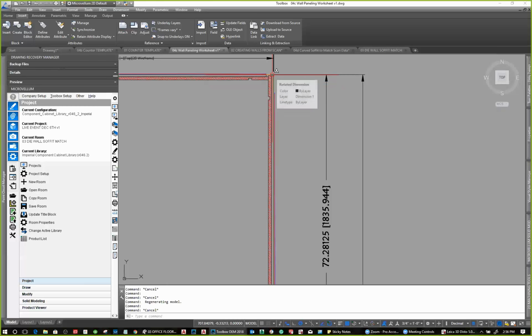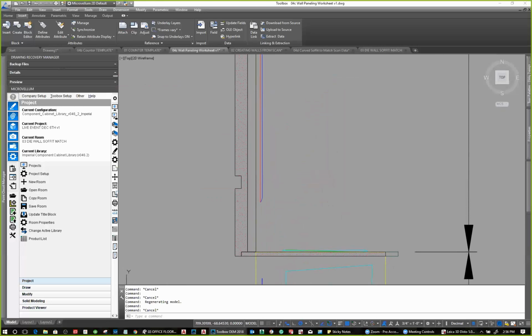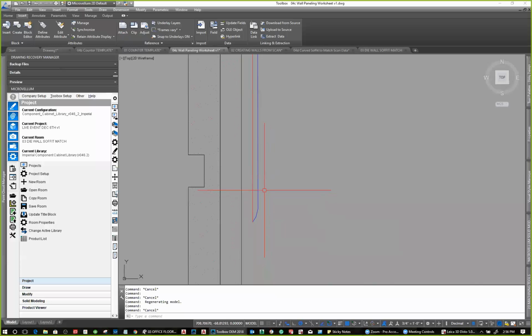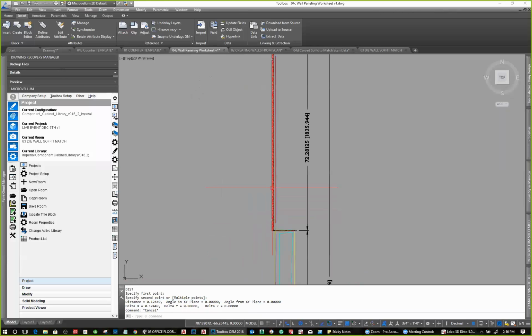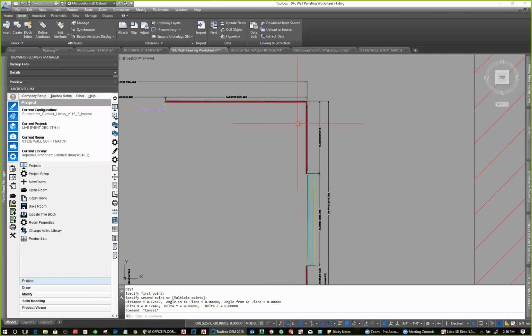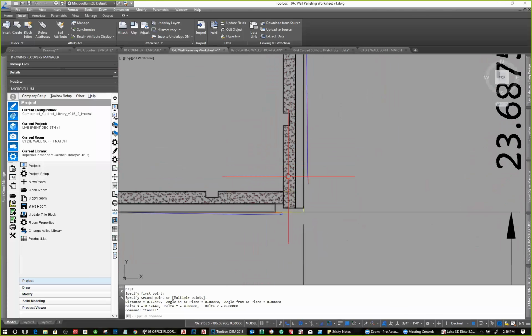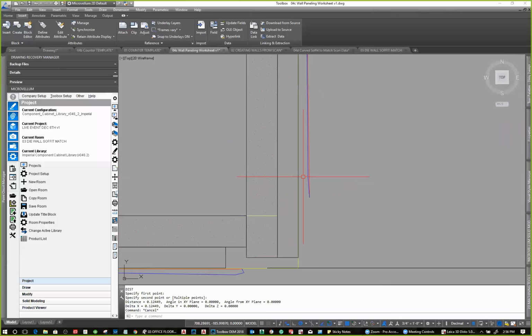So I fit to the corner, and I can come over here and see how off the wall is. And because I changed the colors, I can tell that this wall is out of plumb about 1/8 of an inch. So you can see it down here, this distance. And I went around, and you could tell some areas were a little bit more off than others. And to build this square, we actually had to be off the wall a little bit.